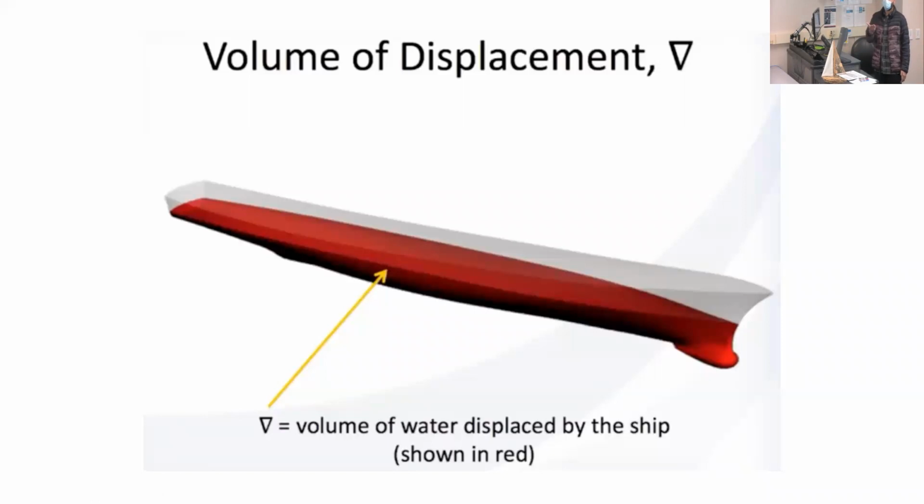The only alternative is for it to find an equation that describes the hull, which is very, very complicated. But a much more straightforward way is to chop it up into pieces and look at individual pieces. So you could basically think of chopping this up into many, many tiny blocks. And these blocks are perfectly cube-like or rectangular shaped. Find the volume of each block, sum all of them up, and you get a rough but very close approximation of what the total volume of this thing is. Okay, so that's numerical integration.